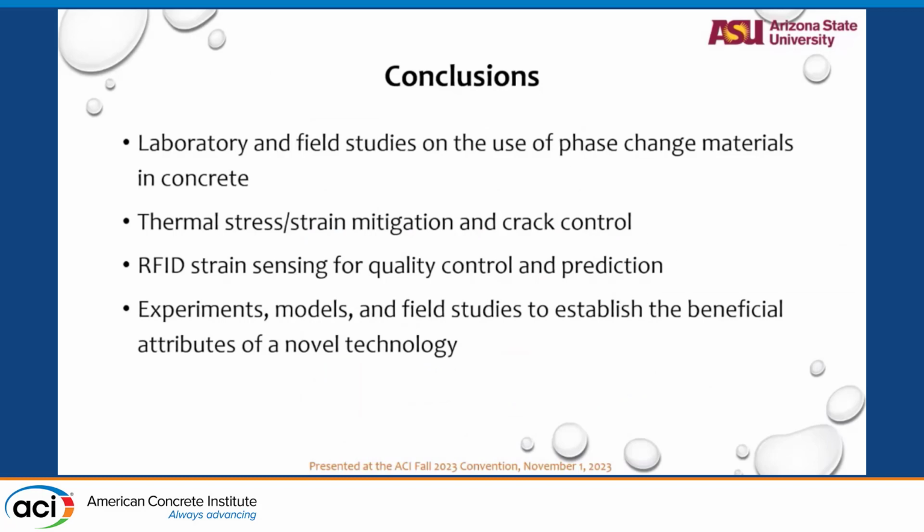So this work helped us get a laboratory test done on the use of PCM to see if we can disperse PCMs well enough into a concrete mix, and if this could help us decrease the thermal strains developed in the mix, such that most probably we can prevent the thermal cracking that happens in concrete. We also developed a system of sensing the thermal strains based on strain gauges and temperature profile.